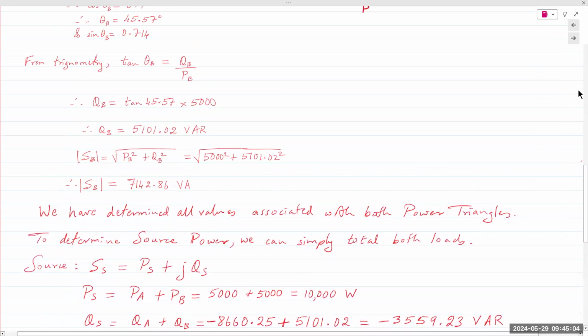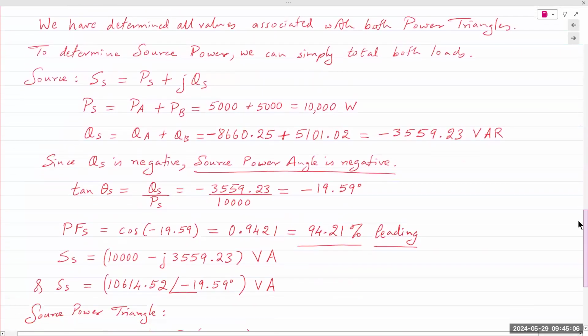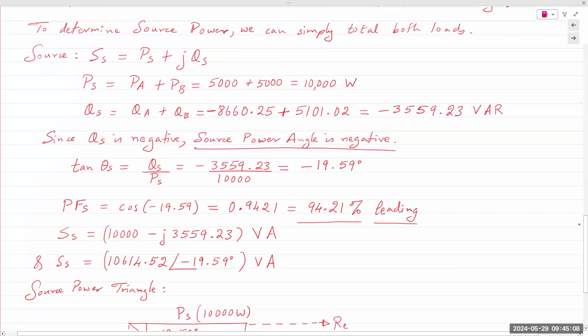So we have multiple loads. The load is just given to us. We're just saying that it's a capacitive and inductive load, but because they have real power, there's also a resistor present in there. But we don't really care about that. We're not given the circuit diagram, we're simply given the system as a whole. So remember, I stated a few minutes ago, if you have multiple resistors, you add everything up together. If you have multiple inductors and capacitors, you add up all the reactive power together.